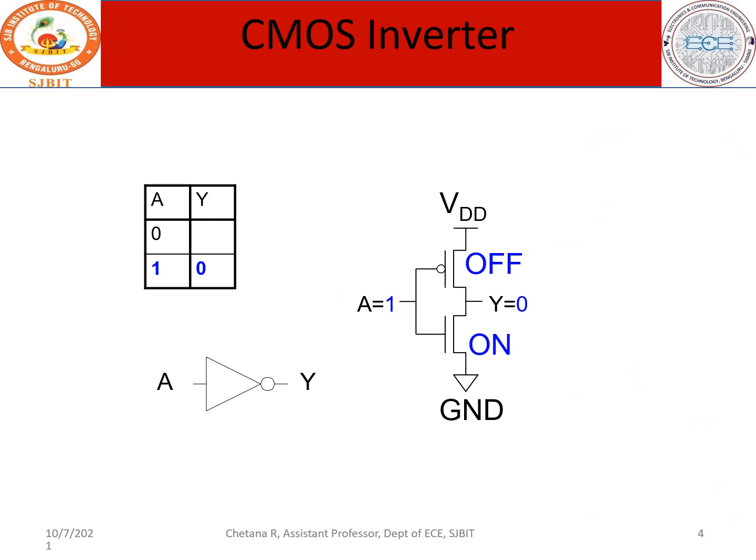Shortly, let me show the representation of how the truth table is satisfied here. If the truth table is satisfied, this circuit behaves as an inverter. I've already told you that NMOS and PMOS are merely switches. So this is your VDD, this is your VDD, and this is your ground or VSS. Ground or VSS, both representations are one and the same. So this is the place for my PMOS circuit, and this is the place for my NMOS circuit, because they are just behaving like a switch.